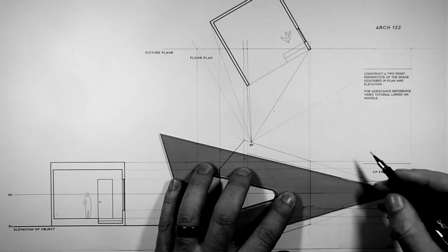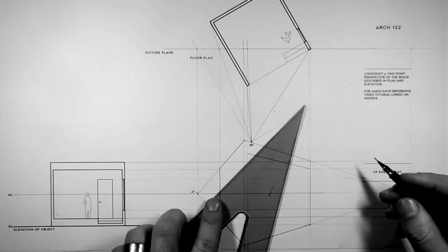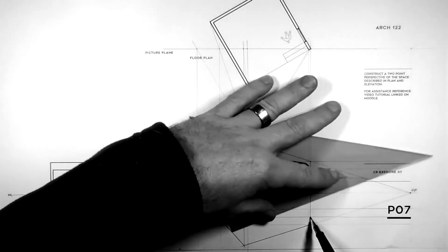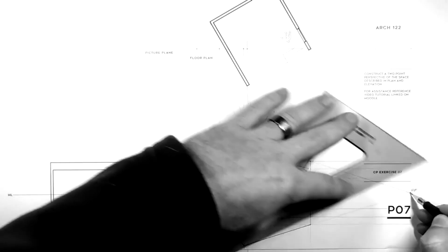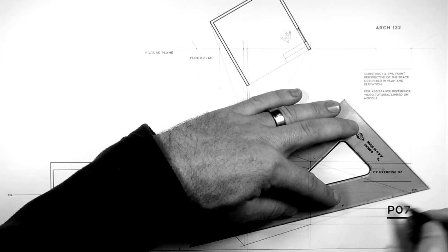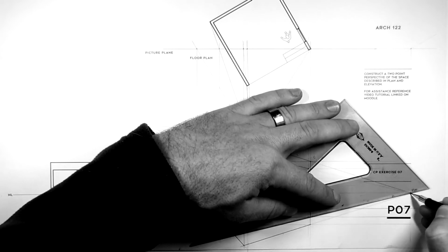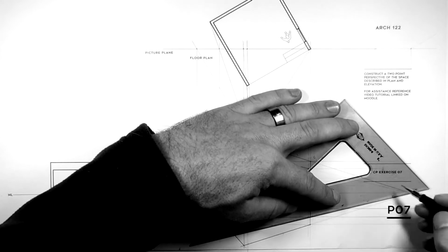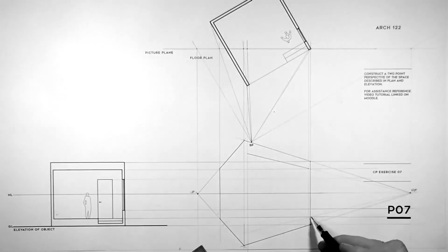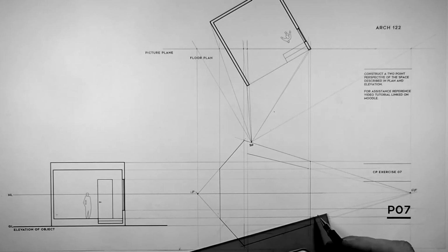Defines our ceiling. And then for the floor, again, we brought the floor height over here. And when that floor line meets the true height line, this outer edge, we can use that intersection. We want to pass through that intersection from the right-hand vanishing point, and be sure to let these line up precisely. And that allows us to locate our ground line here.